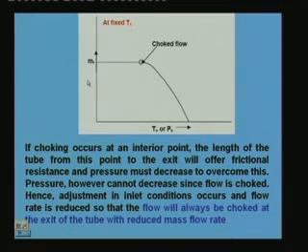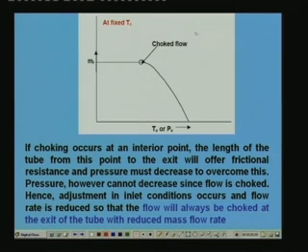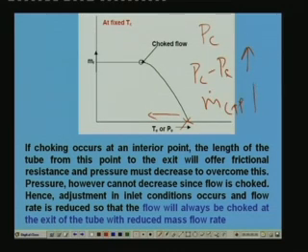Okay, that means if you plot, you can see that if you are fixing the condenser pressure and condenser temperature, and you are reducing the evaporator temperature or evaporator pressure and proceeding in this manner, let us say that this is the initial mass flow rate. As you are reducing the evaporator pressure, Pc minus Pe increases because Pc is fixed and Pe is getting reduced. So mass flow rate through the capillary, as I have already explained to you, increases. Okay, so this process goes on like this, mass flow rate increases continuously, but a point will come at which further reduction in evaporator temperature will not give any further rise in the mass flow rate. Okay, that means beyond this point mass flow rate remains constant. So this condition is what is known as choke flow condition.